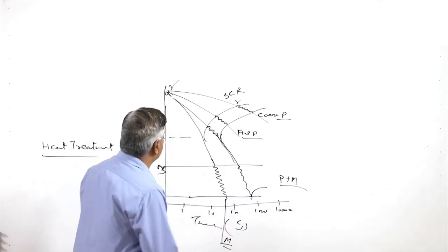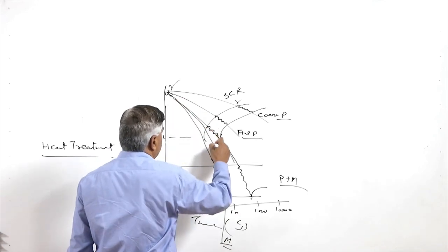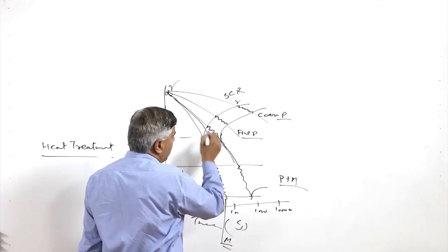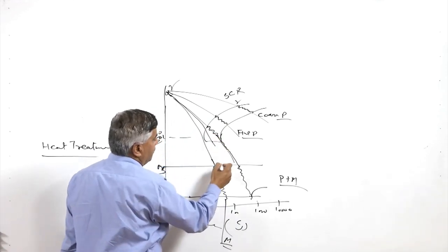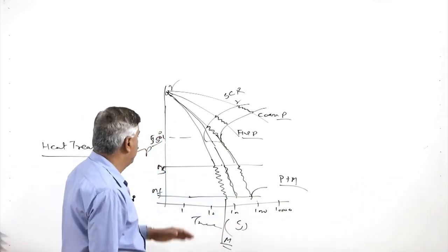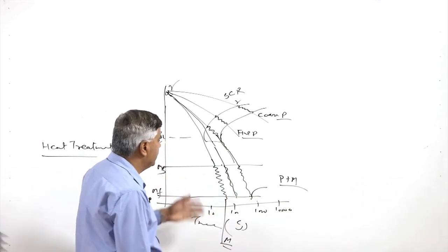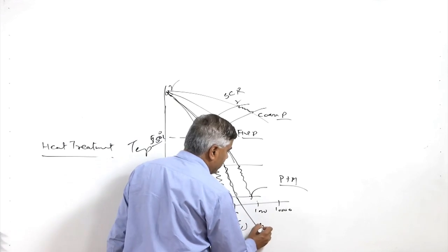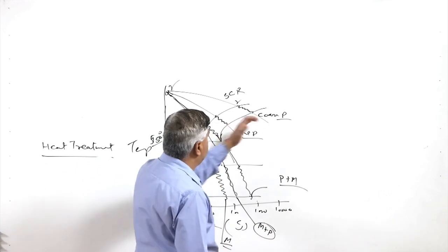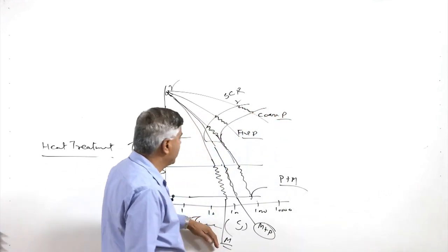If the cooling rate is lower, then it will first form the pearlite, and thereafter the remaining austenite will form martensite during cooling between the temperatures MS and MF. So, martensite and pearlite will be the 2 phases. Since the pearlite is a softer phase as compared to the martensite,